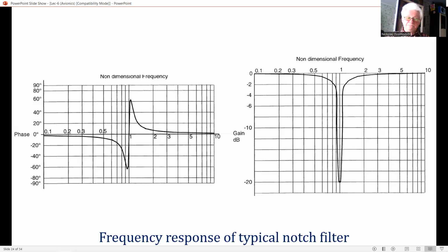The first is sampling delay: the sensor data is sampled intermittently. The second is transport delay: there is always some delay between when the computations are carried out and when the results of the computation are passed on to the actuator. This graph illustrates the phase lag produced by a sampling delay. The mean time delay is half the sampling period. The phase lag produced by a time delay is directly proportional to frequency and is equal to the angular frequency multiplied by the time delay.